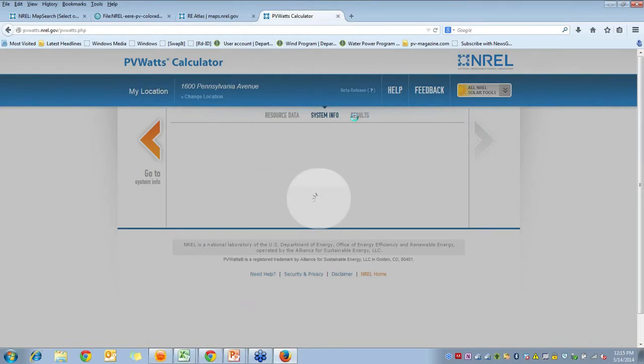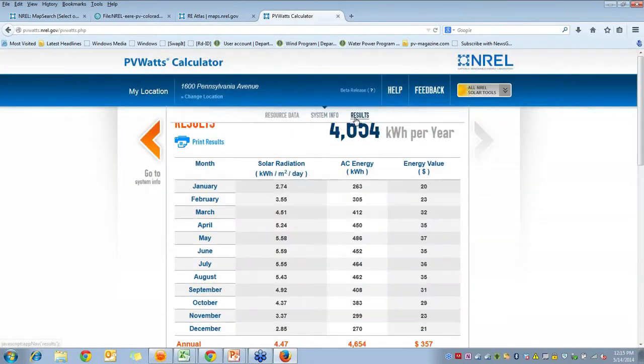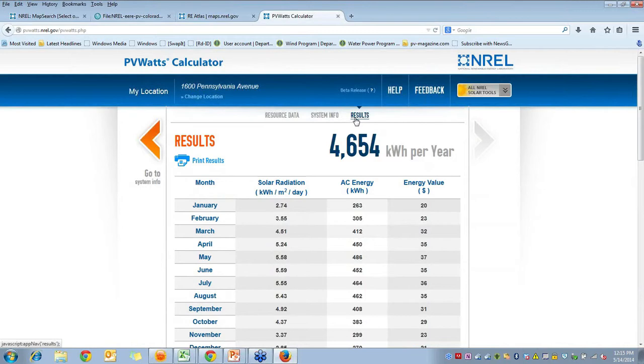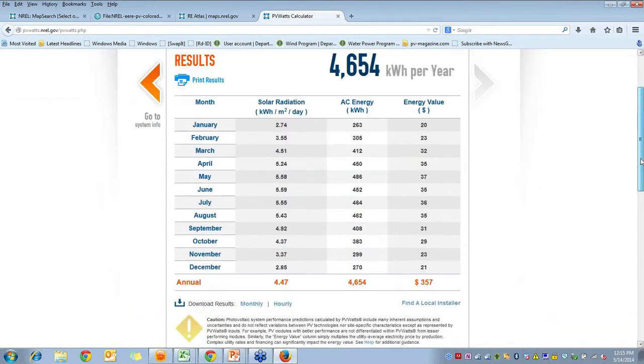And using simulation over a period of 1 year, PVWatts estimates the annual and monthly electricity production of a PV system, as well as the cost and value of the electricity produced by the system. The cost of electricity estimates are based on whether the PV system is on residential or commercial property, its installation costs, and the retail cost of electricity. And again, much of this information is pulled based on the location you entered at the beginning. The tool will provide you with the next step of analysis in determining potential locations for PV systems or projects.